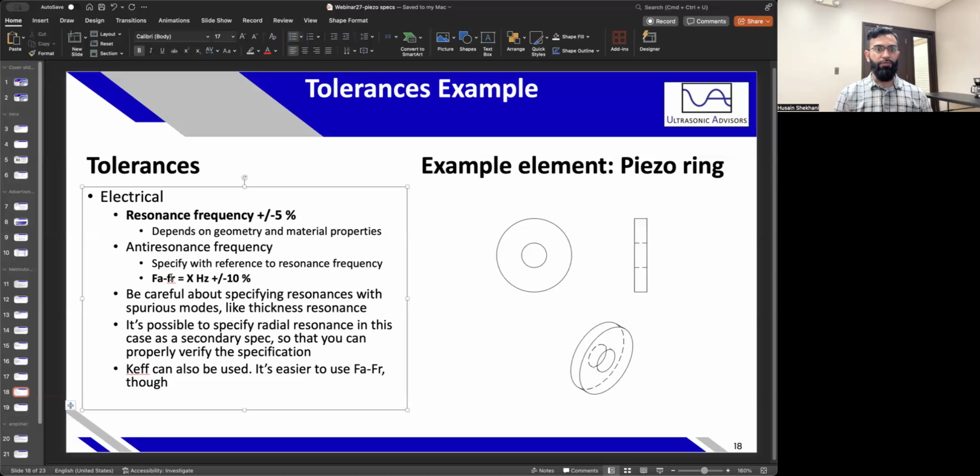to see what happens when you do put the other crystals in. Like if you're using PZT-8, you might choose to order some PZT-4 crystals just to see how different material variation affects your device, and what you could do to be more flexible in your final device, given that you don't have as much control over your ceramic elements.